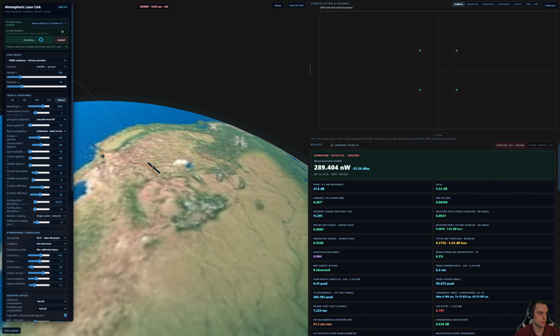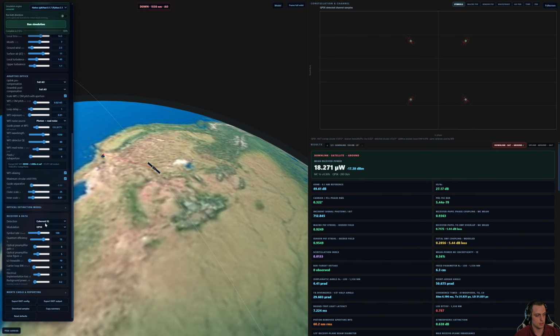And so 0.6 is pretty much the same size as the existing one. That would be somewhat expensive, but you can see we get a very good signal to noise ratio. So their idea was you could go up to 400 gigabits. I guess that would be 16 QAM. You could even pull that off, or you could do QPSK with 2 polarizations. That would kind of give you the same result.